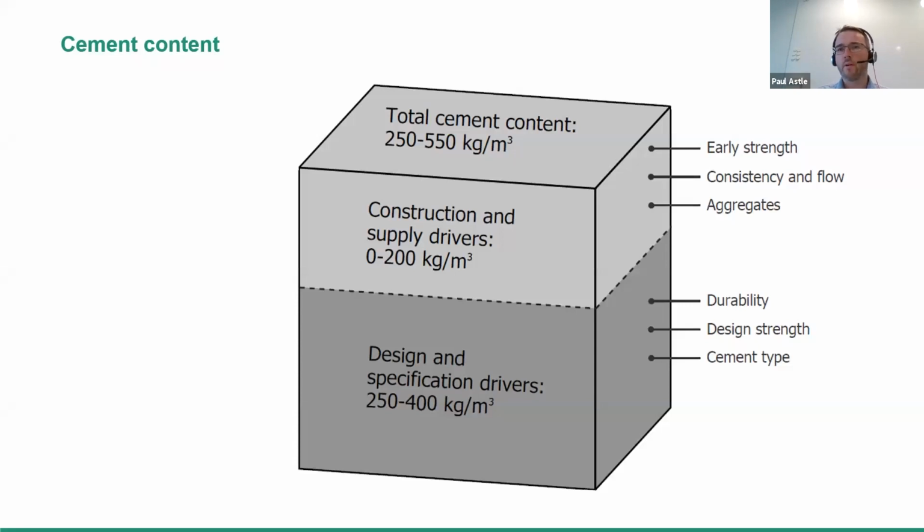And this is really important and often overlooked, because actually you may specify a concrete with a super low strength and think you're fantastic and it's going to be great. But when it gets to site, because of the way they've got to build it, they've got to add in huge amounts of cement to actually make this concrete workable. So that's something that happens already all the time.